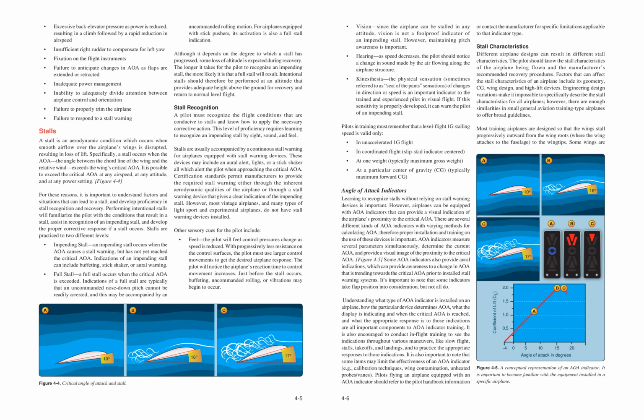Vision. Since the airplane can be stalled in any attitude, vision is not a foolproof indicator of an impending stall. However, maintaining pitch awareness is important. Hearing. As speed decreases, the pilot should notice a change in sound made by the air flowing along the airplane structure.